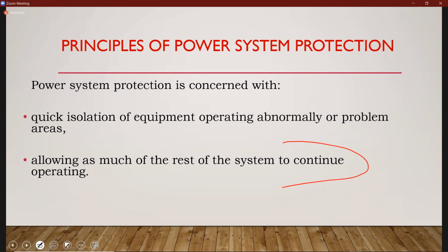However, if that breaker malfunctions, and for whatever reason it does not trip, then what is going to happen is that the fault will now move from just being limited to the living room. That fault will now be a part of the distribution panel. And so instead of just one breaker tripping, the main breaker will trip. And so all the breakers within the panel would lose power. The same principle is applied to your power system.